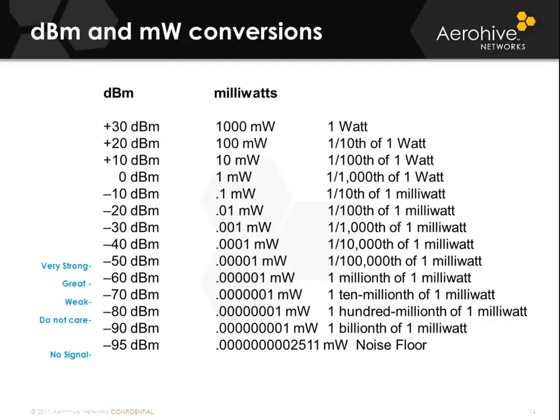If you're using a point-to-point connection in 2.4, you're still limited to 4 watts of maximum EIRP. However, if you're using UNII-3, the upper uniband, and it is a point-to-point connection using highly directional antennas such as a dish or maybe even a Yagi, so it is not an omnidirectional connection, you may be allowed to use a couple hundred watts or more.